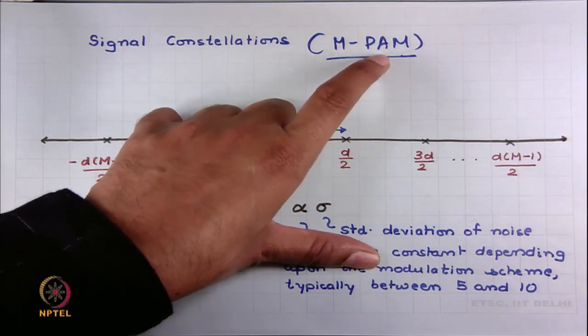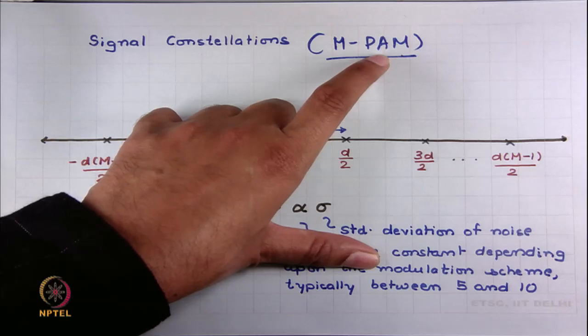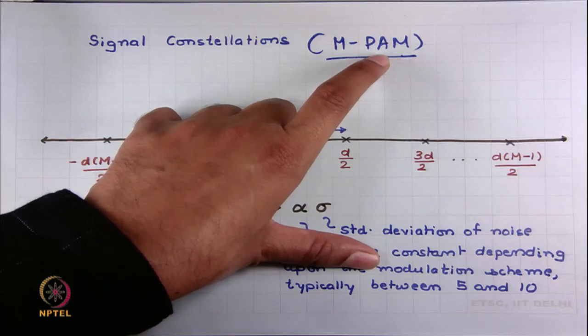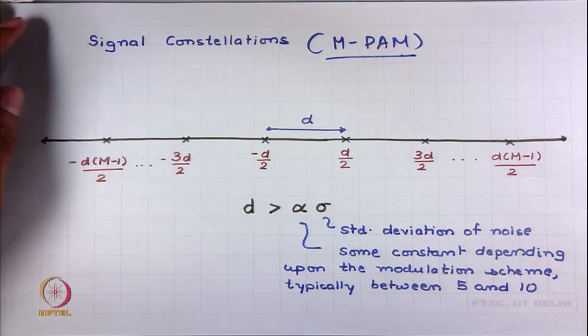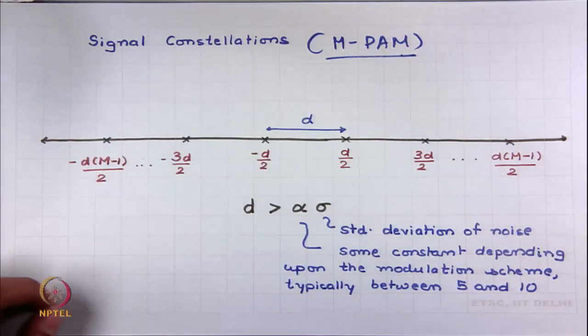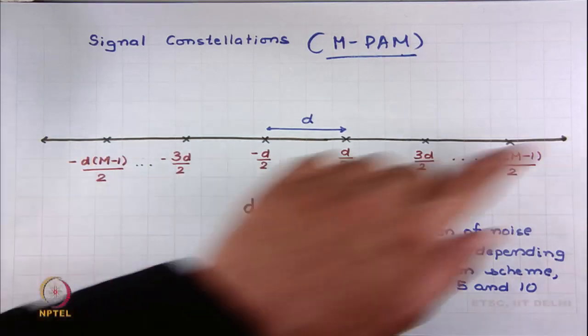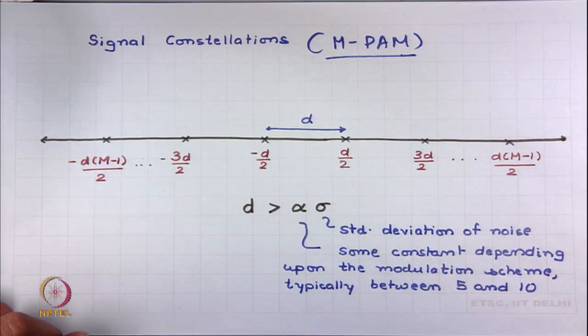Okay. So, this is the restriction. Once you allow the symbols to be complex symbols, then from PAM we go to quadrature amplitude modulation, which we will discuss after we have finished with PAM. But for starting we are talking about PAM, and the basic restriction in PAM is that the signals are considered only to be real signals, or symbols are real symbols, and we are plotting the symbols on this real line. Symbols are quantized discrete time signals, and in literature these symbols and signals are used synonymously, and sometimes we also refer to symbols as signals. So, please do not get confused.